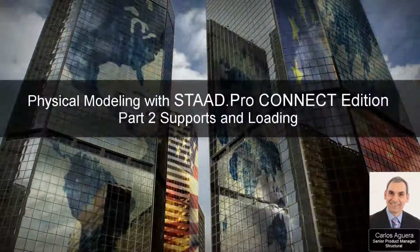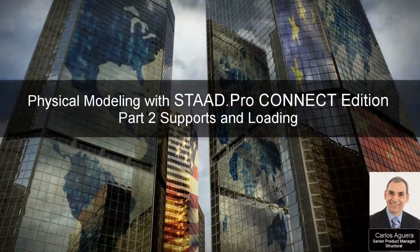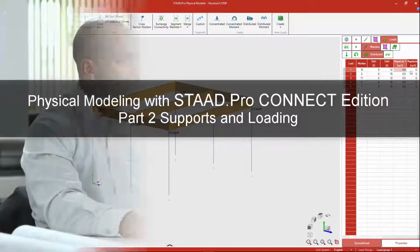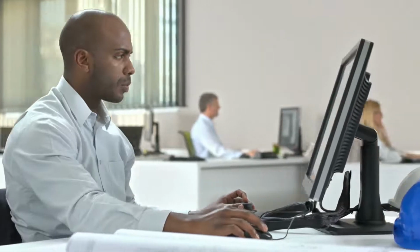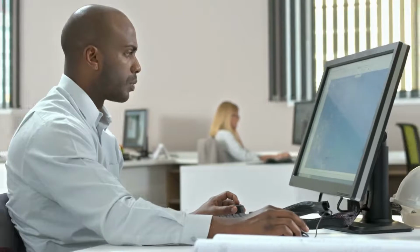Hi, and welcome back to our introduction of using the all-new STAAD Pro Connect Edition physical modeling environment. In this second part of this two-part series, you will see how to assign supports to the base of columns and start the process of assigning loads into groups, which will be used later in the analysis as reference load cases. Watch out for a useful technique on how to make changes which will always be needed as a correction or as the result of a change in the design requirements.